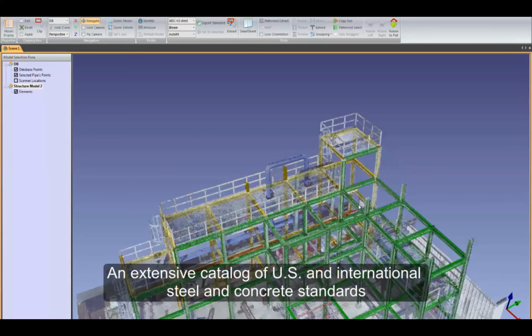Now, if we're talking about two different technologies, let's say we want to combine laser scanning and photogrammetry. We want to combine drone pictures or drone photos with laser scan data. Unfortunately, this may be difficult to handle with ReCap, and I would recommend a better solution, which is Autodesk ContextCapture, that can combine pictures coming from a drone.